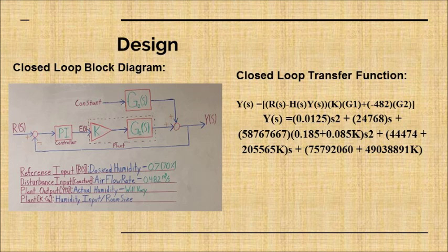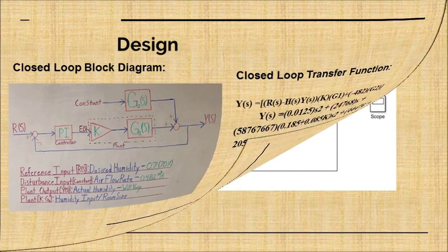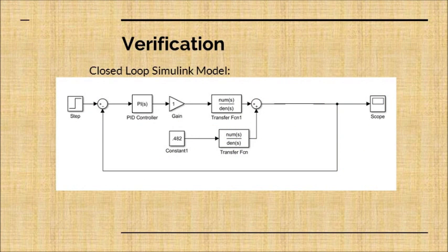We wanted our rise time less than half of a second and our settling time less than 2 seconds. We were willing to sacrifice some rise time in order to decrease our overshoot value specifications. We designed for our steady state error to be less than 1, and we will discuss how we verify this in the upcoming slides. A PI controller has been chosen because it is commonly used in industry for temperature and liquid and gas volumetric flow scenarios, and secondly because of its simplicity.